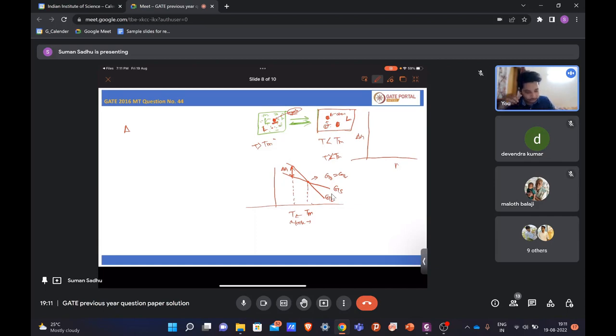That's why when you don't have any driving force, at this temperature you cannot form the solid. So you have to decrease the temperature a bit so that you have sufficient driving force or energy to form the nucleus. So for this we can write that delta G for nucleation is